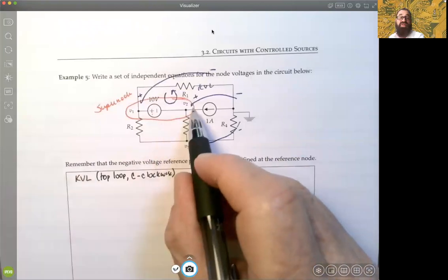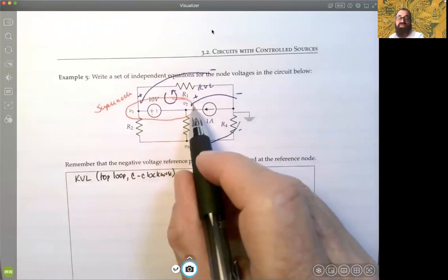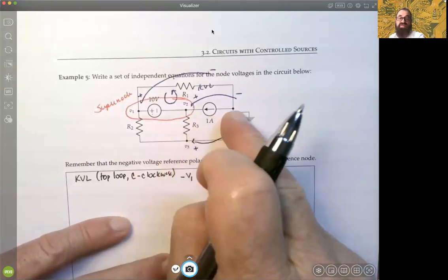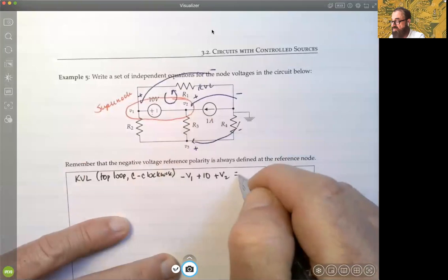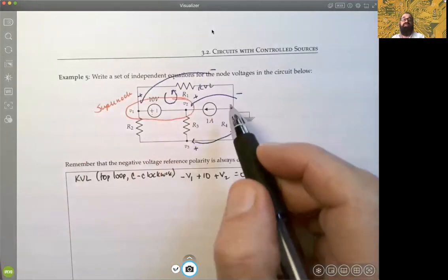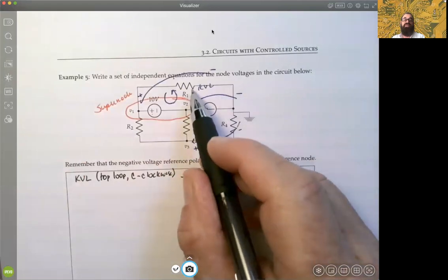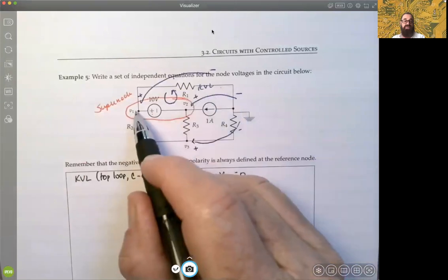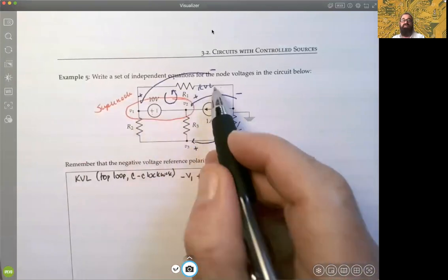Then we're coming into the arrowhead of the nodal voltage of V2, so that's a plus V2. There's no voltage there, I told you, because of the grounding there, and that's it. Okay. Right? Again, this resistance is being connected to the ground, so there's no voltage here. There's voltage over here, but not on this side, okay?